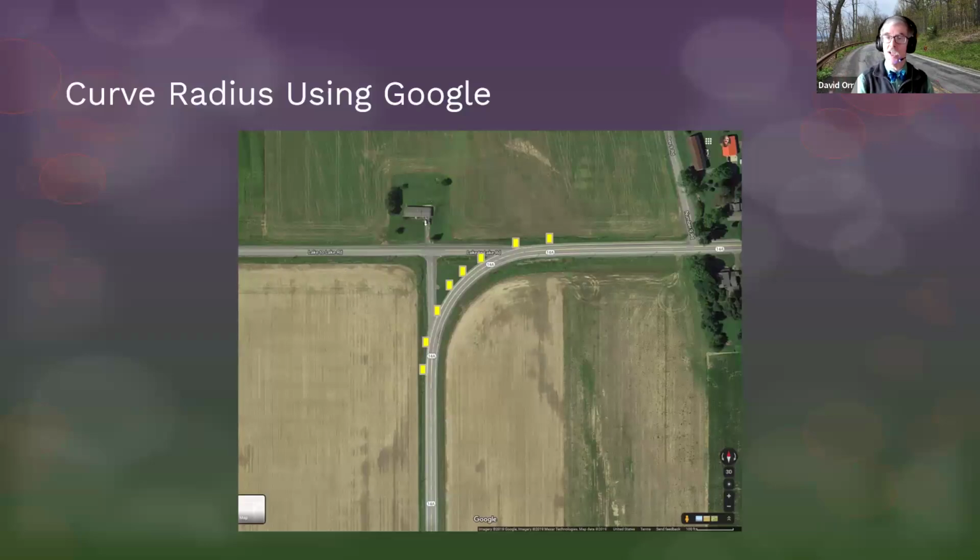That's the real world. That's why I'm saying when you go back to look, make sure you think about being able to see at least three of those delineators slash chevrons at any given time. And that's really going to help you out. The other thing to make sure of is make sure your chevrons or delineators go all the way around the curve. Way too often I'll see as I'm driving around, the chevrons stop short. And so they don't take you all the way back to the point of tangent, to the end of the curve. And again, you want to give drivers good information where the end of the curve is.